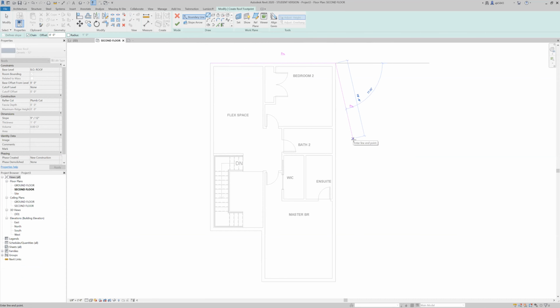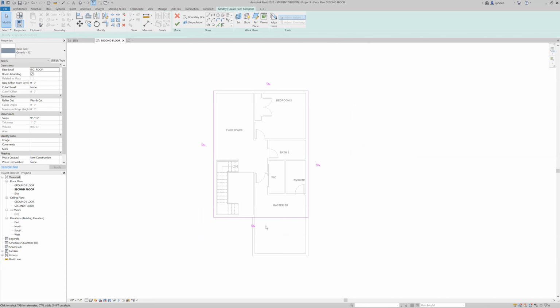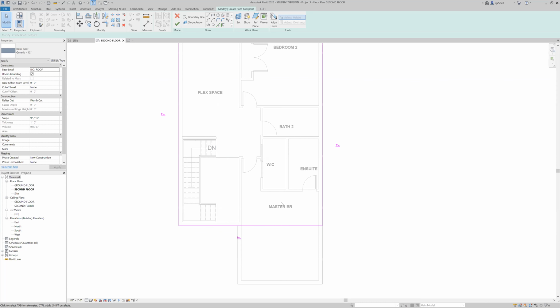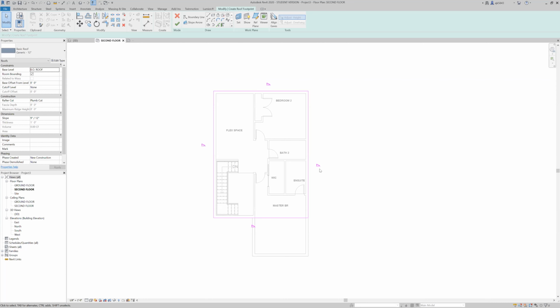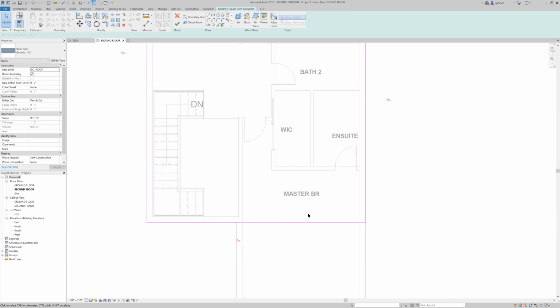So we'll start by drawing the bigger portion of the roof, and so we'll take probably a little bit of work to get the angles right that we need for that join between those two roofs to work. And we'll need to make sure that all of the defined slope options are correct as well. So right now we want all of these roofs to slope up so that they intersect on top. So I think all of these primary lines are going to have these slope functions selected. The one that we don't want selected is going to be this right portion of the master bedroom because we want that to pitch at a triangulated angle.